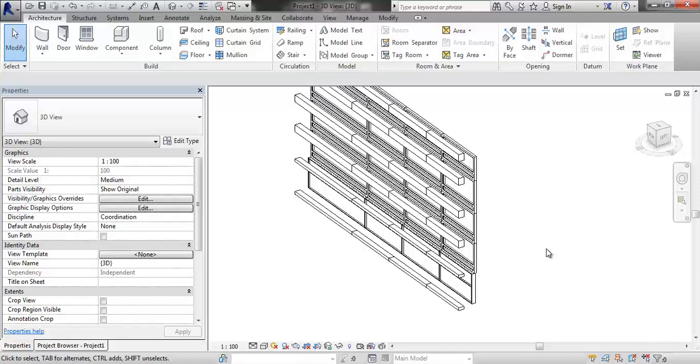Slab edge covers, there, right? So that's a family, right? That's going to host all other elements. Now to make the louver system, I'm going to start at a generic model, and I'm going to build within that generic model one single louver extrusion.